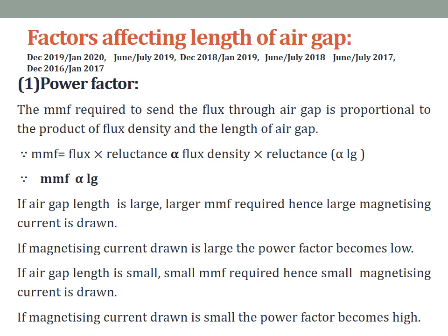What happens if proper air gap is not given? The rotor may touch the stator. If proper alignment of the shaft is not there, then the rotor may touch the stator. That is the reason a proper air gap length has to be given.